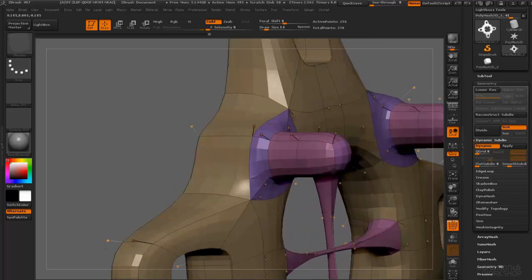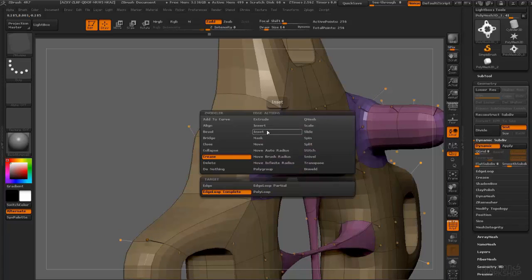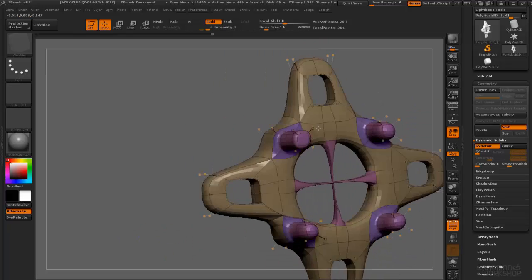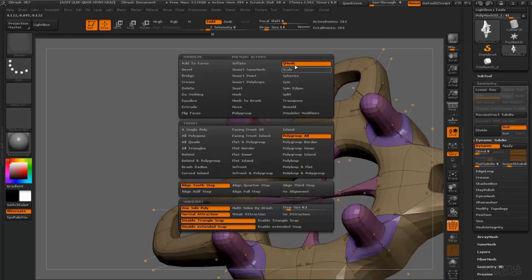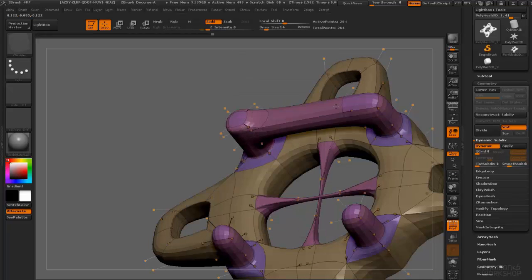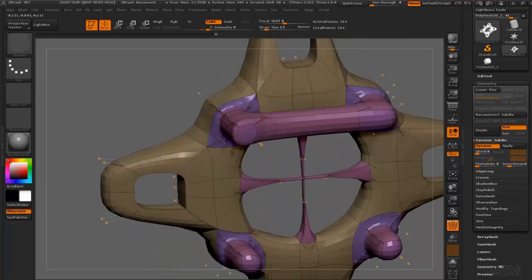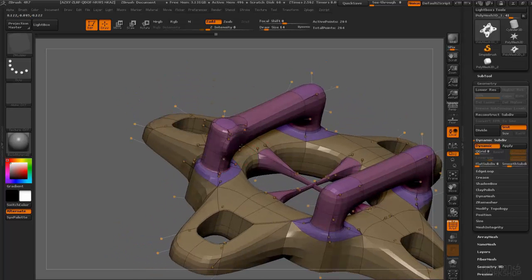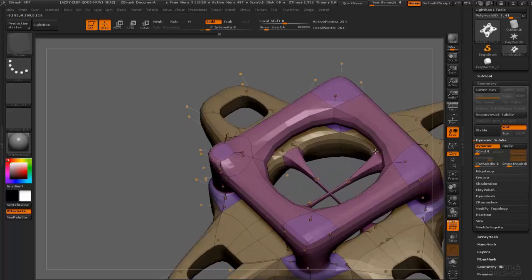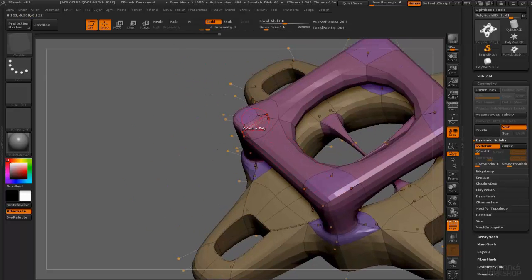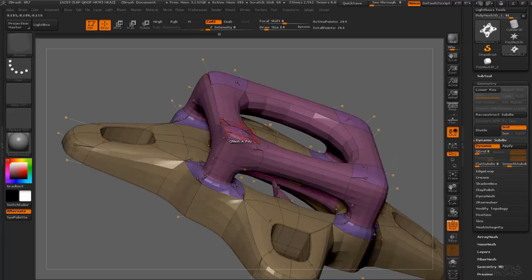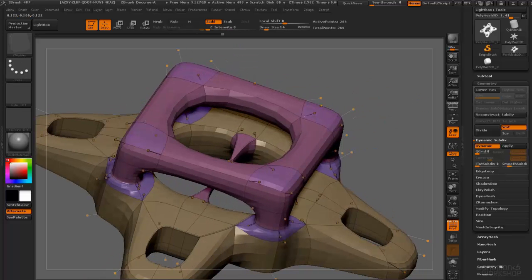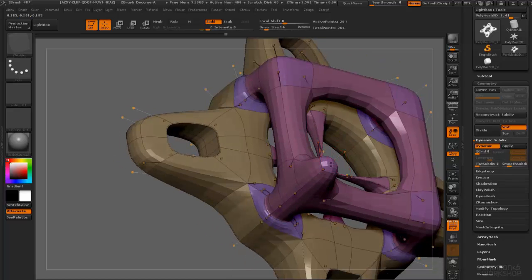Now let's say that I want to cut an extra edge loop in here. I'll just select the edge and click Insert, and I can click and insert new edge loops in here, and that's going to sharpen those edges. I'll go back to QMesh, single poly. If I QMesh and bring that across, look what happens. It automatically snaps and connects to the next mesh that's closest to it. There you go. You can do the same here. I'll just grab that, stretch it across, and you can see that it starts to snap and connect to these points. By the way, if you've got an extrusion here that you want to get rid of, simply select it and start extruding it back. QMesh is smart enough to take that extrusion and then flatten it back down.